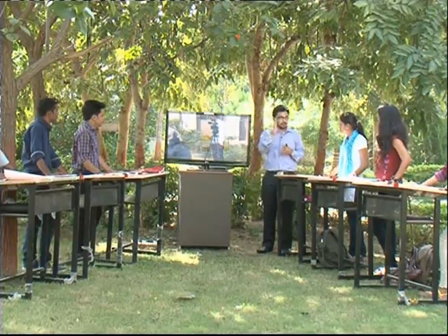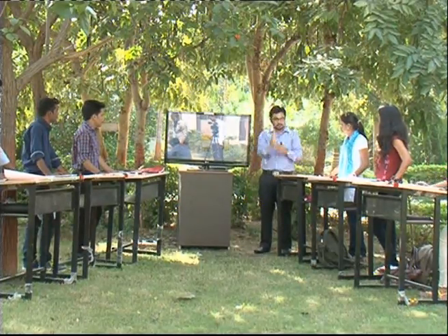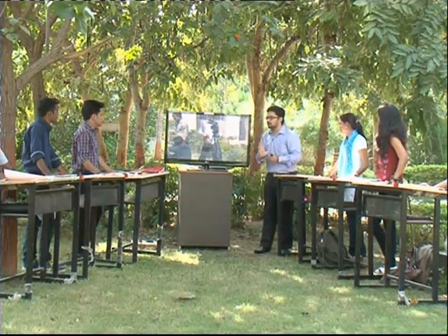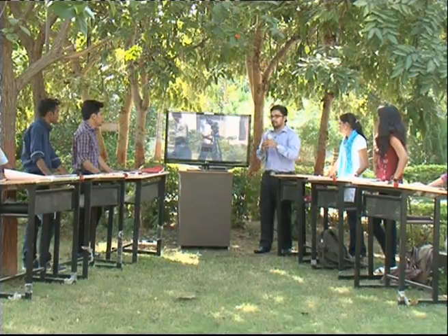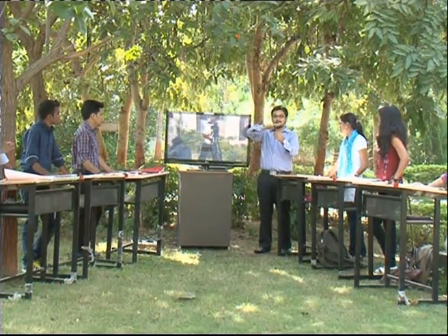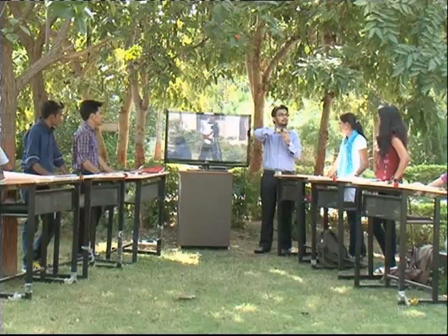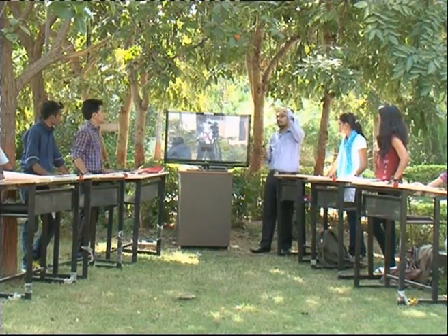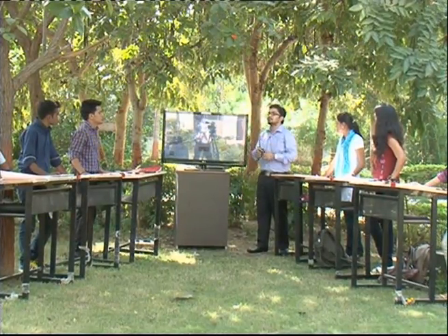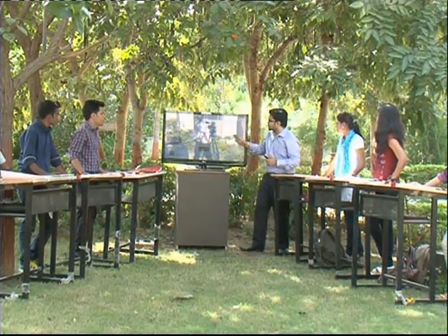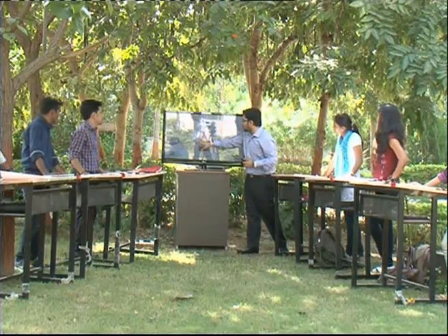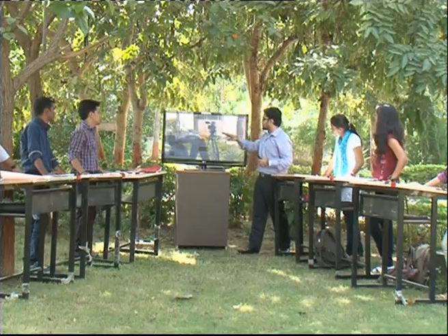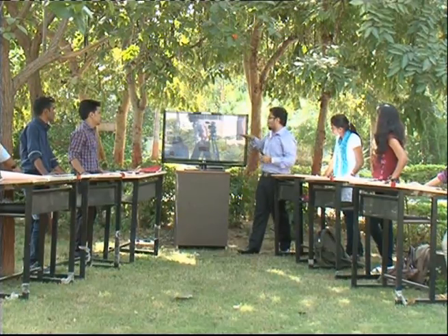Earlier we were passing a plane parallel to the axis of the cone from the center vertically. Now I will take a cone and a plane and cut that cone exactly horizontal to the base of the cone. If I view it from the top, what I will have is a circle. Here it is shown that O, B and B dash is a cone, and I have used a plane A dash to cut the cone horizontally.